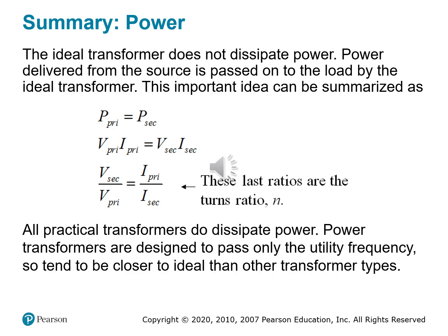So every time you calculate voltage or current changes in a transformer, you're applying power in equals power out, or at least power in is approximately power out. This is very, very close. Again, not considering the power losses. Real transformers aren't perfectly efficient. No component is. They have core losses, copper losses, and sometimes leakage inductance.